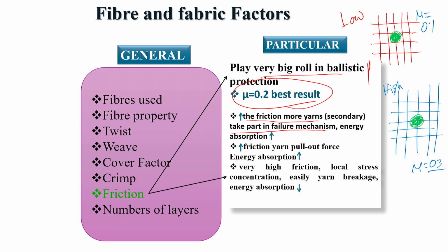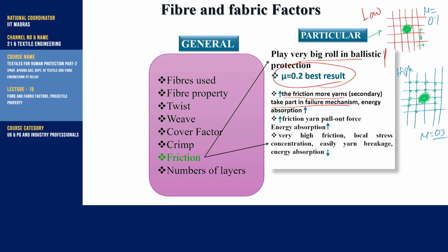But in case of higher friction, we can assume there is a high friction and a more prominent locking will be there. So, this total structure will act as a unit structure, but here there will be thread to thread movement. With low friction the entire structure will not act as a unit.